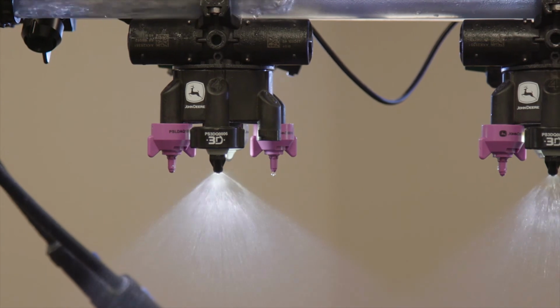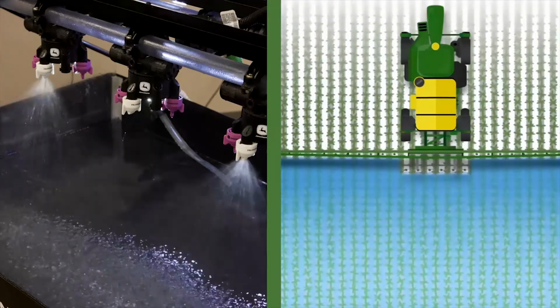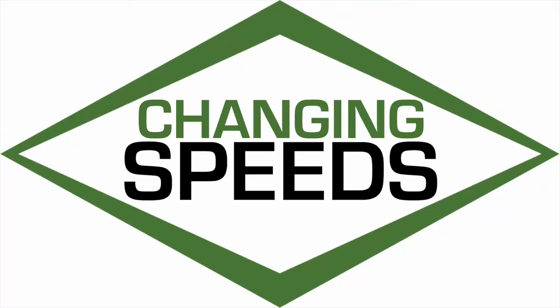The left side is showing a higher flow rate, the middle's kind of halfway in between, and the right side has a decreased flow rate to compensate for that ground speed. In this example, we're looking at automatic nozzle switching, or auto select. What's nice about this feature is we have the ability to automatically select nozzles to keep and achieve the proper speed based on our application ground speed.